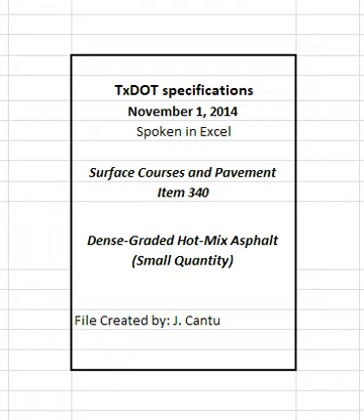2.7.1 RAP. RAP is salvaged, milled, pulverized, broken, or crushed asphalt pavement. Crush or break RAP so that 100% of the particles pass the 2 inch sieve. Fractionated RAP is defined as 2 or more RAP stockpiles, divided into coarse and fine fractions. Use of contractor-owned RAP, including HMA plant waste, is permitted unless otherwise shown on the plans. Department-owned RAP stockpiles are available for the contractor's use when the stockpile locations are shown on the plans.